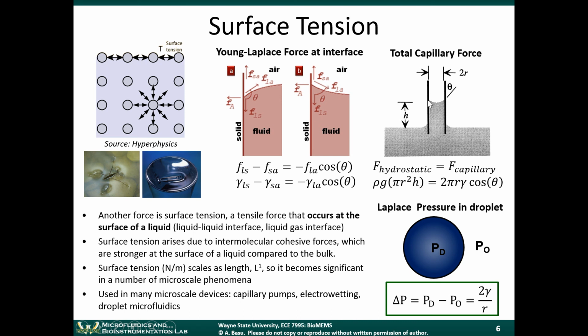So if you zoom in on one of these forces here, the water molecules are actually exerting a force on this whole volume of fluid, because the water molecules are trying to go to the surface here, and they're pulling other water molecules with them. This tension on the surface of the water, the surface tension, is actually pulling the fluid up when it's a hydrophilic surface. If it's a hydrophobic surface, the opposite happens.